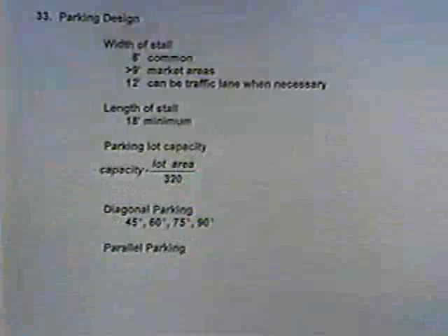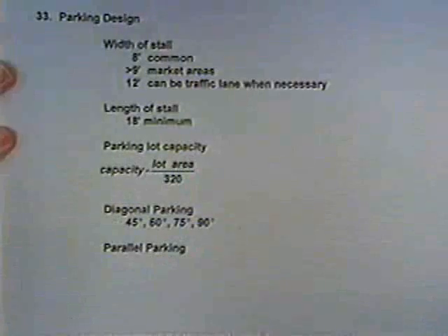We talk about parking design in section 33 in your reference manual. Typical widths of parking stalls are 8 feet. You'll find them slightly wider than that, maybe 9 or 10 feet, in market or shopping areas. And they can be as wide as 12 feet when you have a traffic lane adjacent to the parking space.